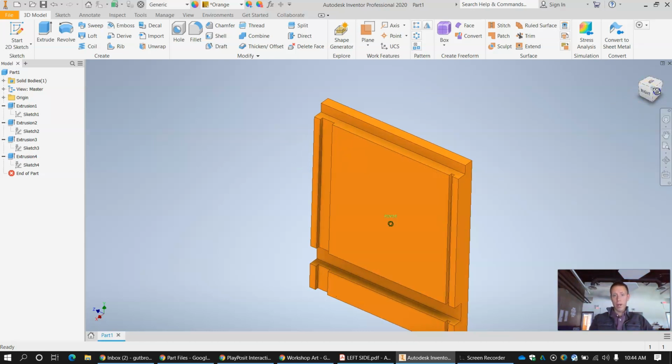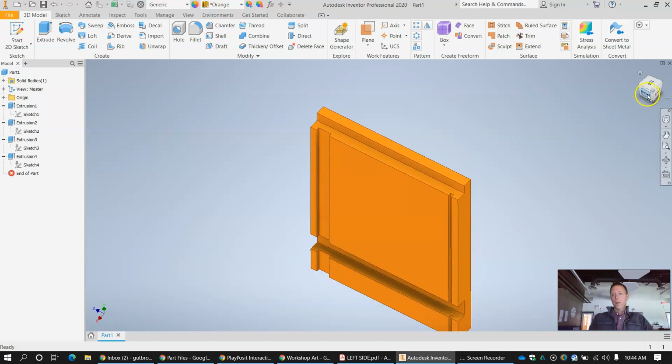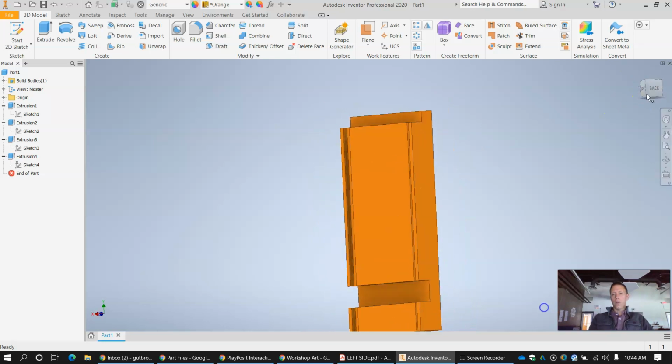Notice how I adjusted those using the browser. Let's say the last one was I wanted to adjust the height of this. Again, I don't go back, clicking the back arrow. I don't go mess around with this. I don't add another sketch. I don't go, ooh, 2D sketch, another 2D sketch. No, that's not how you do it. You go back to how you originally decided the height of this thing. The way that we originally decided the height of this thing was in sketch 1, not extrusion 1. Extrusion 1 told us the thickness of the board. Sketch 1 tells us the height of this board.